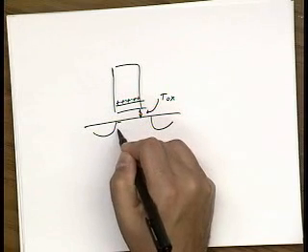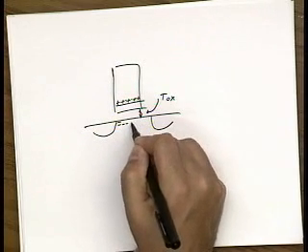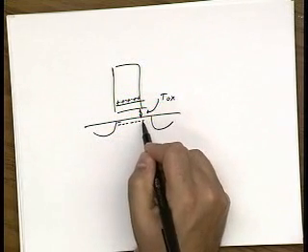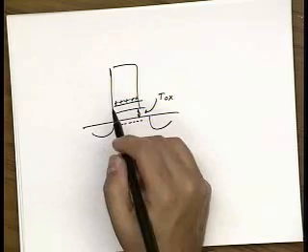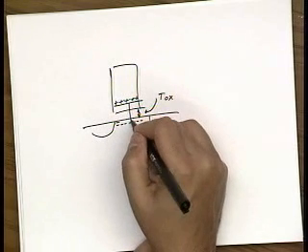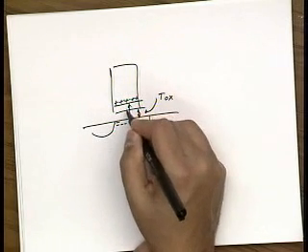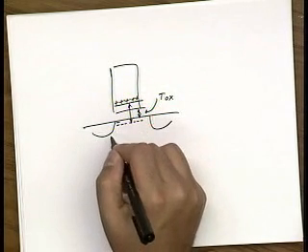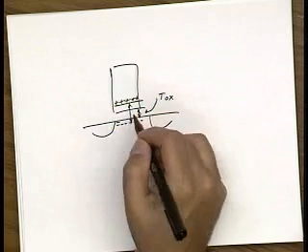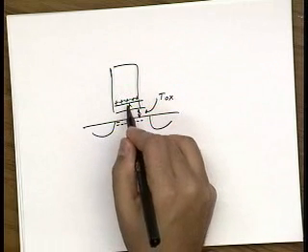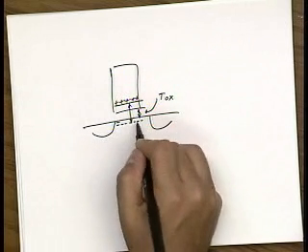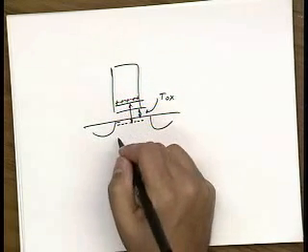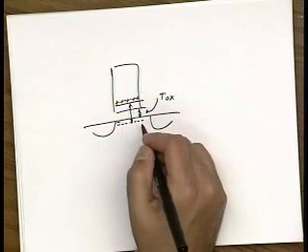And in fact, because of quantum effects, quantum confinement, the electrons also can't go all the way to the surface. They actually are just a little bit away from the surface. So the actual oxide thickness for a transistor is higher because of these two effects. And these two, in fact, are bias dependent. So as you change the gate voltage, then poly depletion changes, and also the mean position for the electrons changes. You kind of pull them closer to the surface, even though they don't like to be there.